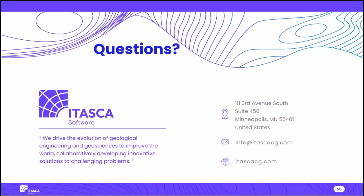The first question: can Maxwell damping be used with the Mohr-Coulomb model to do seismic time history analysis for reinforced soil walls? Is the phase velocity issue significantly affecting these results? Yes. For the second application, the 2D site response, I used a Mohr-Coulomb model combined with Maxwell damping, and the result is quite good. I didn't see significant phase shift for that example, because for a typical soil deposit the natural frequency is not so high, so that is not an issue.